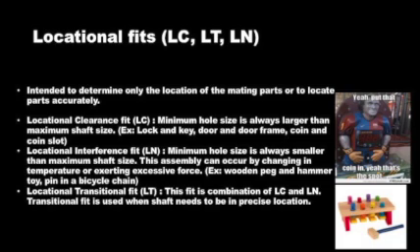Locational clearance fit is when the maximum limit of the shaft is less than the minimum limit of the bore diameter. Locational interference fit guarantees the shaft and bore will interfere at every point within their tolerance zone. To achieve this, you may need to use excessive force or change in temperature to expand the hole. Lastly, the locational transition fit is used when a shaft must be held in a precise location.